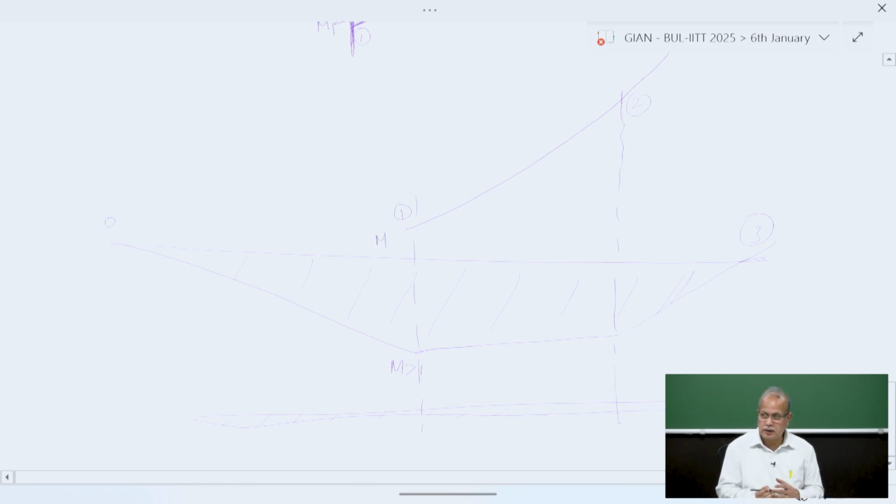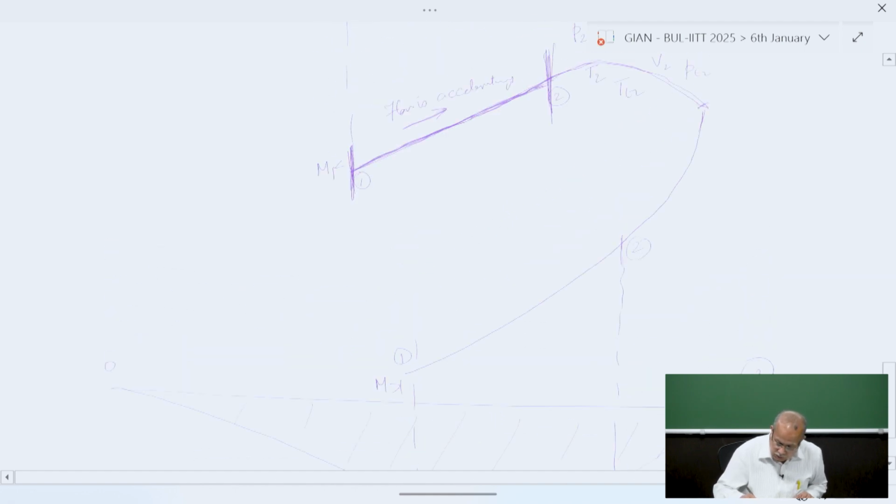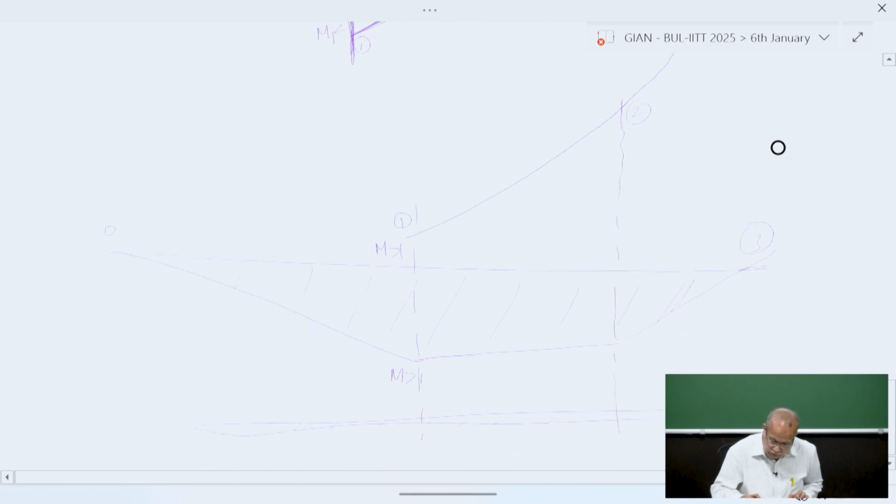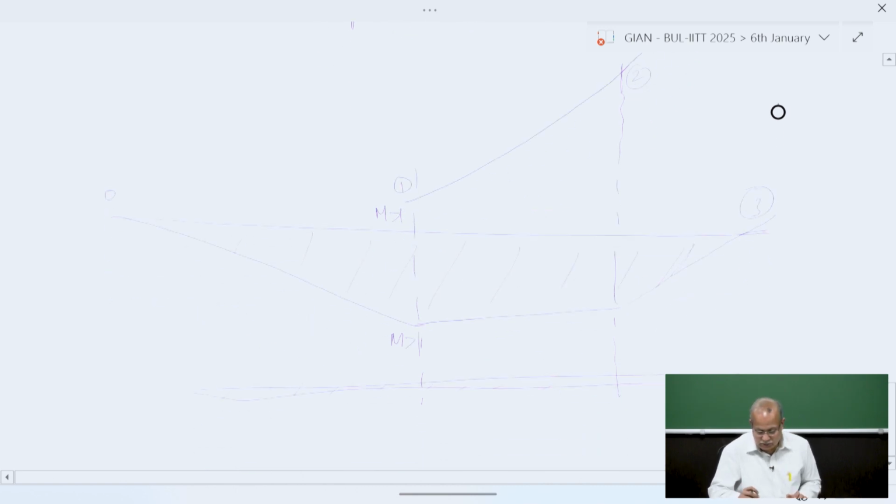The lower branch of the Rayleigh line is supersonic. The addition of heat will cause the supersonic flow to decelerate. Eventually, in the theory, it will reach M equal to 1, which is the critical condition. That is the theory. So now we can see that with the Rayleigh theory, we should be able to solve for the main combustion parameters.